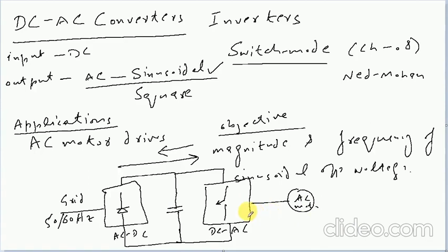That is possible when, for example, the motor, which is the load connected to the output of the inverter, is slowed down. The kinetic energy associated with the inertia of the motor is recovered. This is when the braking operation takes place, meaning when brakes are applied to the motor or it has been slowed down.